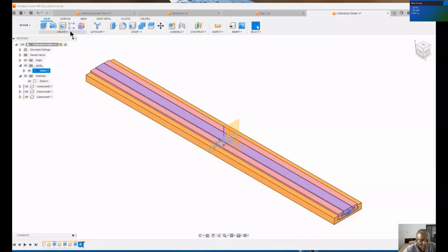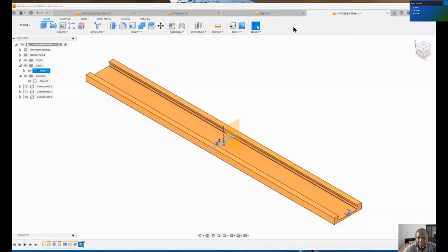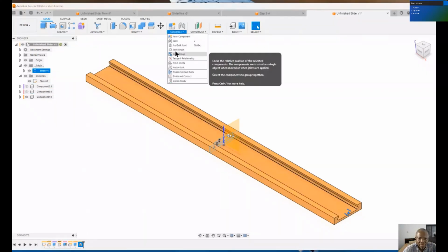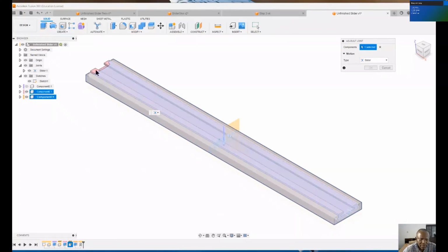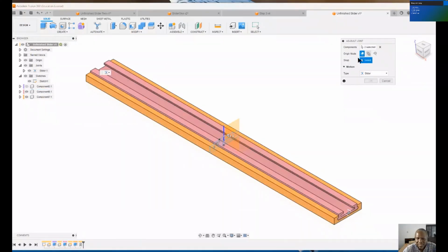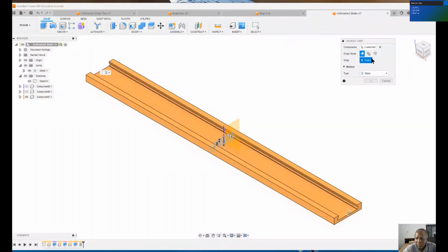We want to do the same thing for the remaining two slides, for the other surface, the meeting surface. So the first thing to do is to switch off the first two, and then if we create an assembly, now it's as built assembly, and then we select components, this component and this component. So two components have been selected, and then to select the snap, we can select the point here as the snap, and then we now select the surfaces for the meeting, the motion surfaces.